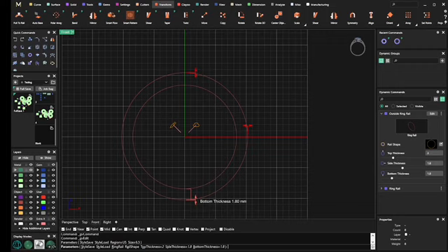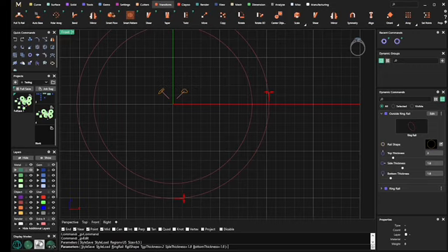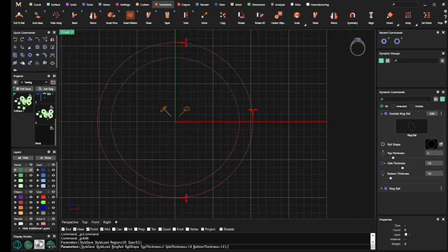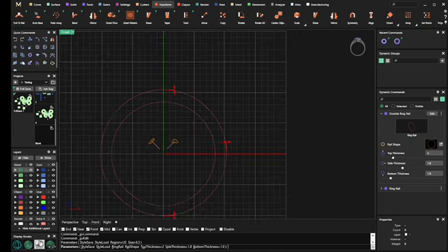For example, if it's a 5-carat diamond ring and it has a lot of metal around it, a lot of stones, I probably need to have the back of the ring a little bit thicker in order to balance it out to keep it from spinning so badly. But a lot of rings, especially like an engagement ring, I will do 1.6. Typically, the finish of the ring, it's going to finish 0.2 less millimeters. So it'll finish at about 1.4, 1.45. I usually just allow 0.2.